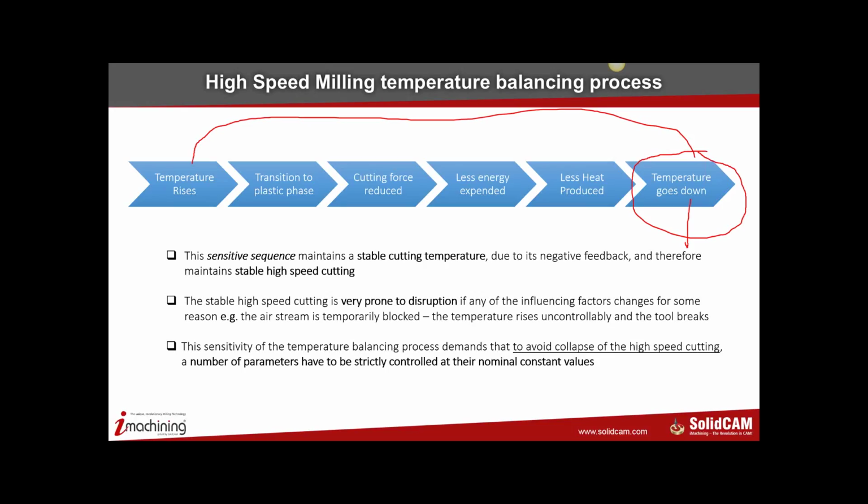Of course, there are several things that are needed to maintain the equilibrium. You can't have equilibrium without cooling, because cooling is very important here. If the cooling is switched off, your story is likely to go back to the first stage. And if it actually goes back to the first stage, you're going to have a catastrophic effect on your tool. Your tool is going to simply disintegrate because it can't take this change in thermal stress on itself.